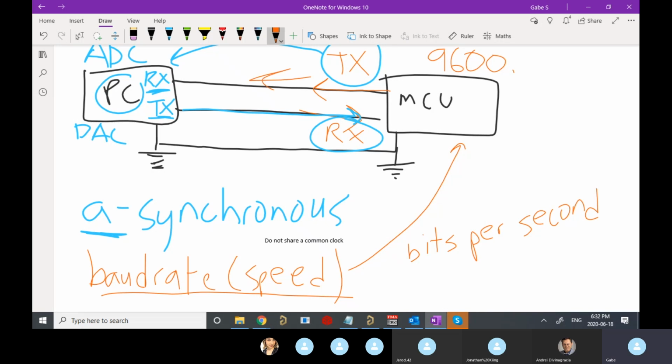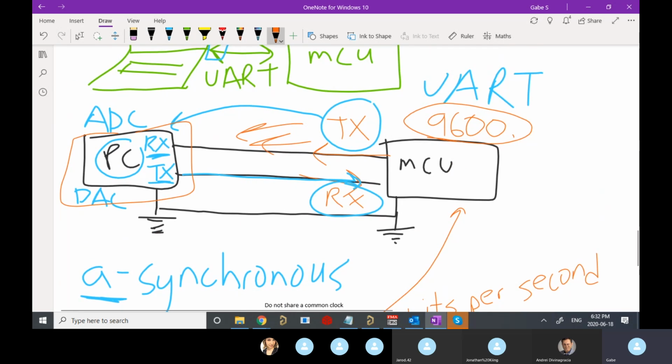And so those are going out 9600 times a second. And this is configurable, this 9600 up here. Now, whatever you're talking to needs to agree, needs to say initially when it's first set up, hey, we agreed, we're using UART and we're using it at 9600 bits per second or 9600 baud rate. If we accidentally pick something else, let's say I picked a higher baud rate, maybe a lower baud rate.